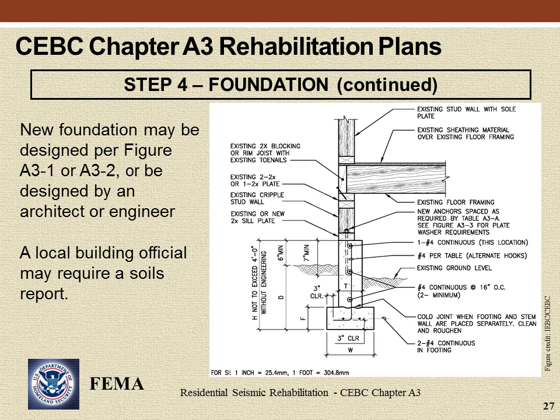CEBC provides two details for new foundations where existing foundations are found to be inadequate. Detail A3-1, shown here, is a concrete foundation with a concrete stem wall. Detail A3-2 provides a concrete foundation and masonry stem wall. All details of dimensions and reinforcing are provided. Foundations could also be designed by an architect or engineer.